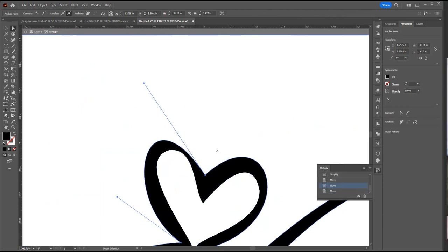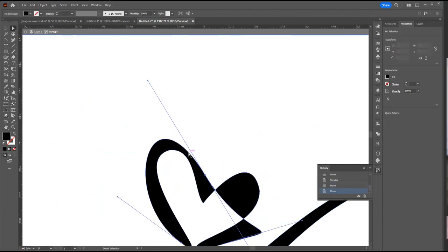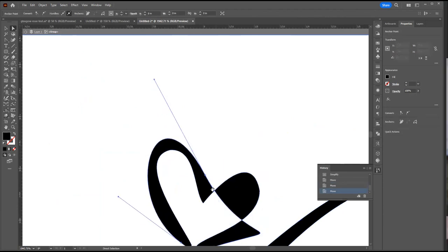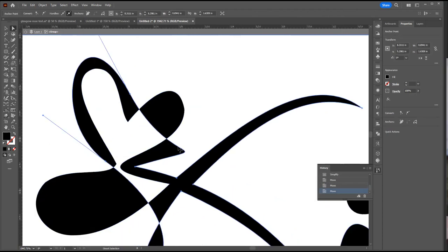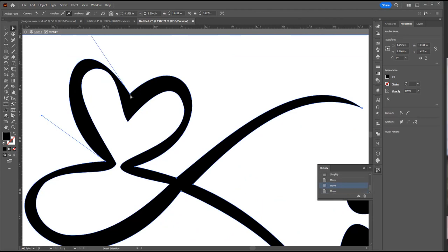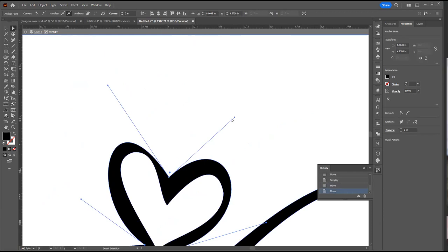And what we want to do, if we can, is we just want to pull the little part up here. Now, if we do that, it's changing the angle of this. So first of all, what I'm going to do is I'm going to click on the point and I'm going to see, oh, look, that one is going that way. So when it's such a sharp difference between the handles, and obviously that's making this V curve, then I'm going to use the Shift C, and this is the handle tool.